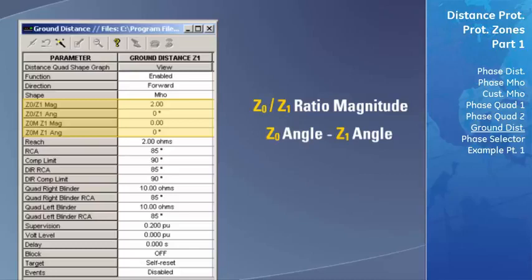Since the positive sequence impedance is another line characteristic setting that had to be entered into the relay, these zero sequence settings are entered as a ratio of that positive sequence impedance setting. The following 2 settings are used to configure the zero sequence impedance for the zone we are configuring. These settings allow the D60 to accurately perform the zero sequence compensation used to ensure the zero sequence ground path will be included accurately in the impedance calculations.